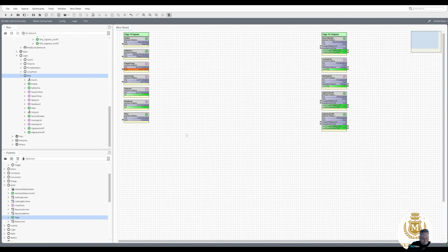Now I've had some emails about fan coils. So we're going to write a little bit of fan coil logic. We're still using the Edge 10. Now the Edge 10 is a great controller for fan coils. It's not that expensive. It's one of the cheapest of the Niagara Tridium range, and that's only because it has 50 points maximum capacity and 3 devices.